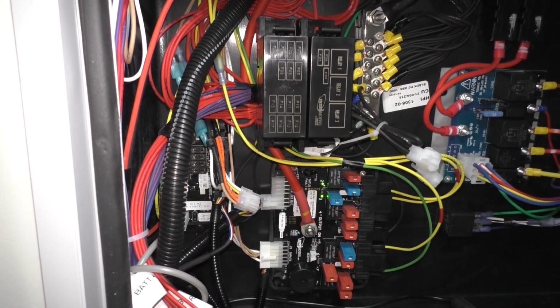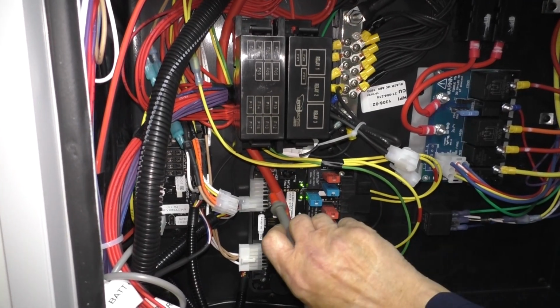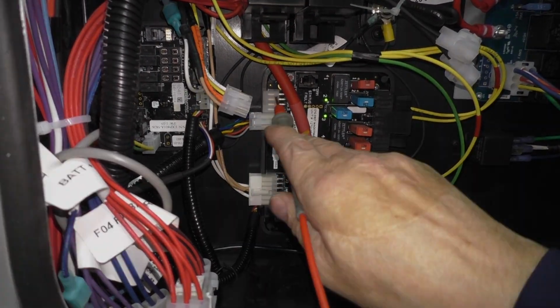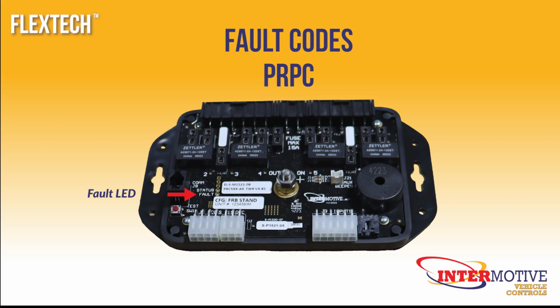With the load unplugged, you can also check for power on the pins. Once you verify the output is functional, you'll know the issue is with the wiring, or you may have to reduce the LCO load. You can also use diagnostic mode to determine the issue. Page 1 will display LCO status. The last number in the 3-digit fault code tells you which LCO is having a problem.